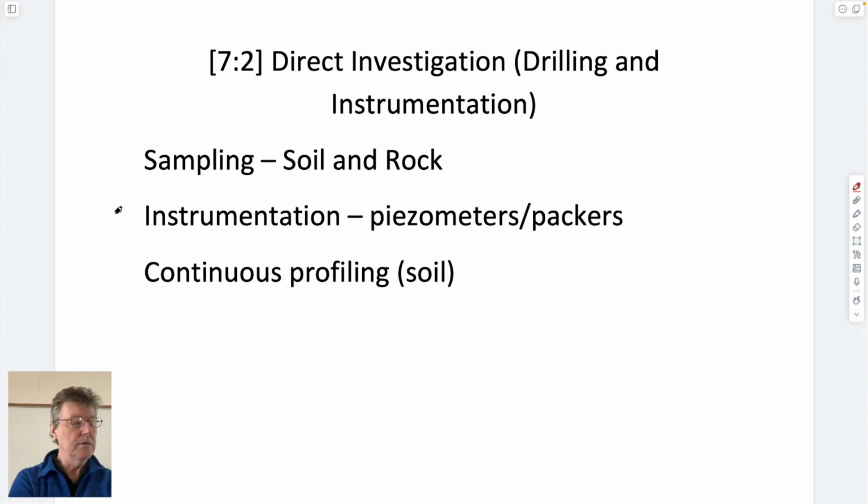All right, so let's get rolling today. We said that the last three sessions would talk about investigation. The first two would be on so-called direct investigation. The first one we talked about was trenching and drilling, and we talked about the fact that if you want to drill a hole to get down through the strata, to perhaps leave a hole to put instrumentation in, or to directly sample the strata, then you might trench or drill.